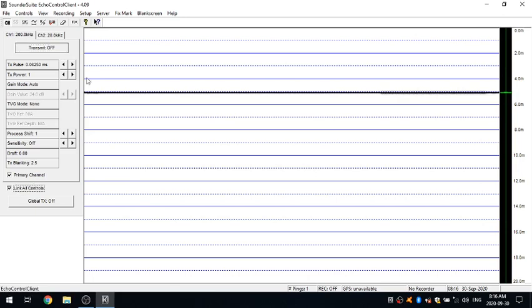If this is active, what it'll do is it'll make sure that both channels are operating at the same settings. So if you make a change to one channel and you go to the next channel, it'll also be changed to that same parameter setting. This comes into play if you're working with side scan, where you want to actually get your port and starboard to both work at the same parameters. And global TX, by clicking this, you will actually activate both channels at once. And it just gives you the option of control of both channels, similar to your link all controls.